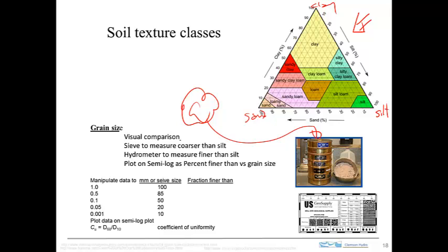And each one of these pans right here has a sieve at the bottom of it, and there are, I guess, about 6 or 7 of these. Each one has a sieve of a different size, and so you shake it and the soil goes through these sieves, and then you weigh the amount of soil that's retained on each one, and that gives you a size distribution. When you get down to fine material that's, say, very fine sand or silt, and then you want to determine what the silt and clay fraction is, you generally have to use a different technique where you suspend this fine-grained material in water and allow it to settle out, and the rate at which it settles out depends on the grain size, and you use that process to determine the fine grain fraction. Okay, so that's one way to determine the fraction of sand, silt, and clay.